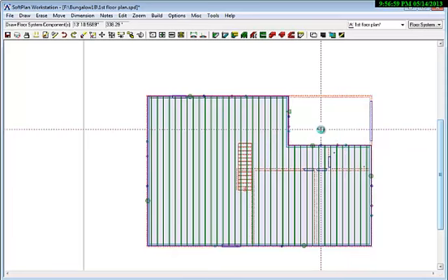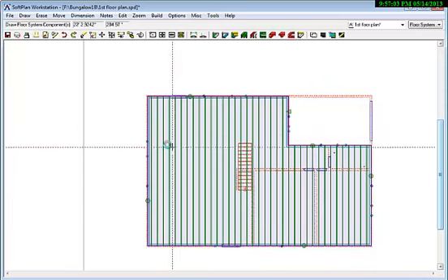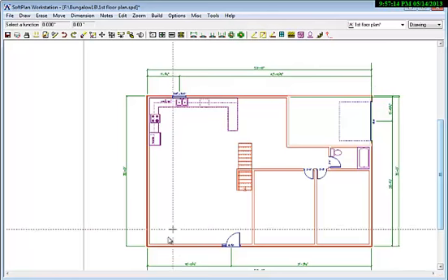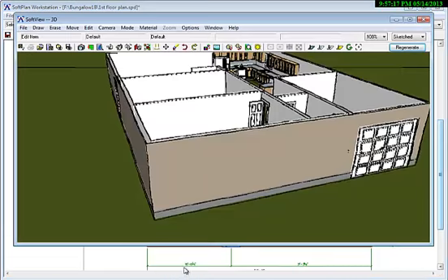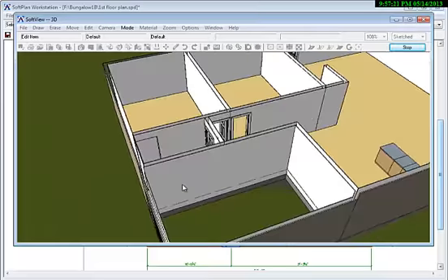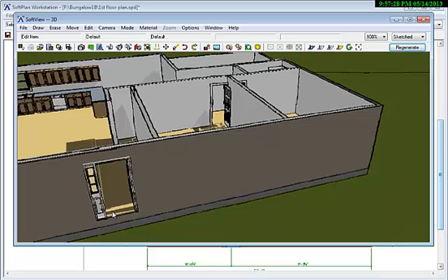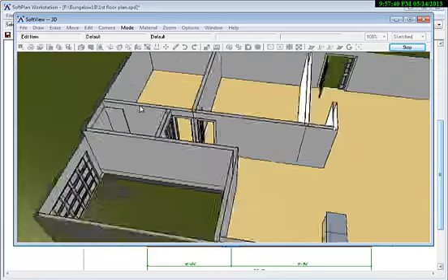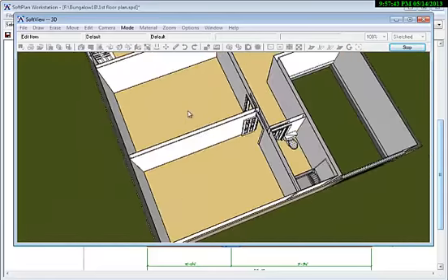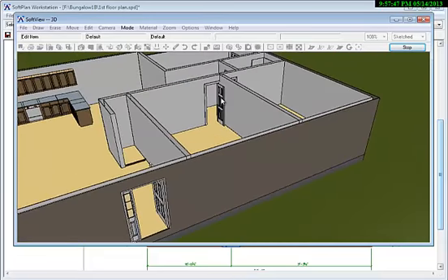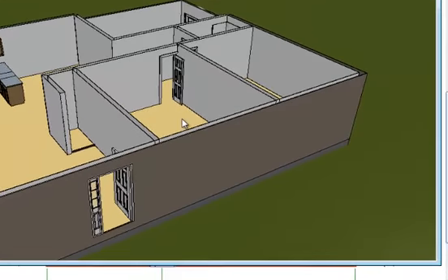Of course, we don't want a floor system in the garage. We've already got the slab, and you can do all sorts of changes with this. If you wanted to change the direction of the floor joists and so on, then you could do that, but we're not going to bother with that now. And so now I'm going to go back to drawing mode, and let's see what the effects were. Here we've got now a floor system, and notice that our door has now moved up, because of course it's got to move up to the top of the subfloor, and so it's taken that all into account, and it's moved up our kitchen cabinets and made all sorts of adjustments for us, and that's why we did it in this order rather than doing the floor system before we did the basement. You could do it that way, but then you have to make a fair number of adjustments.